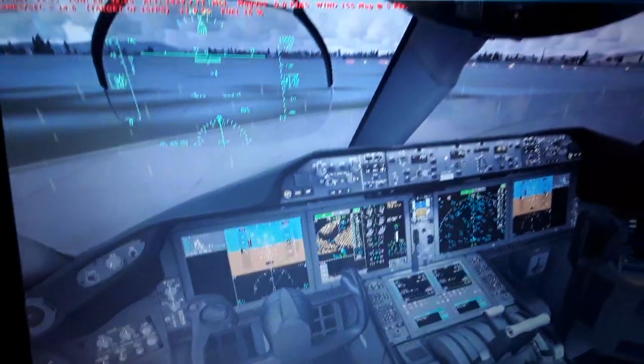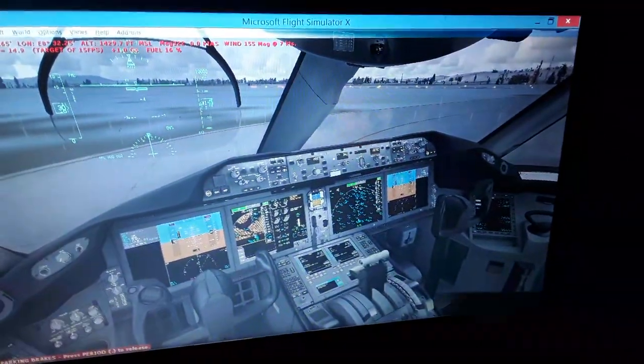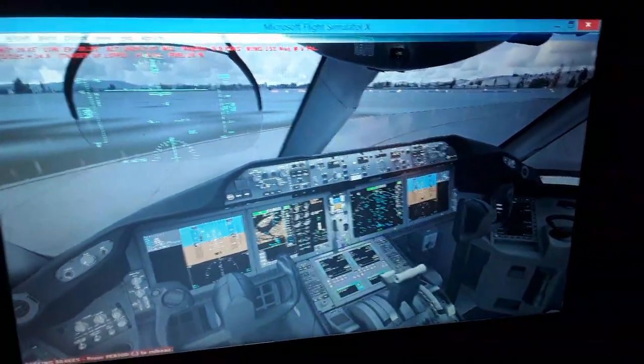We're gonna be flying the aircraft at an airspeed 2 or 3 times faster than that at sea level. We're gonna be having higher intake of airflow from the front fans of the engines. So we're gonna be having a different fuel air mixture requested every second. This is adjusted by the FADEC, the fuel air mixture, the fuel metering unit, the fuel flow to the engines, as we use the thrust levers here to command the engine's thrust.